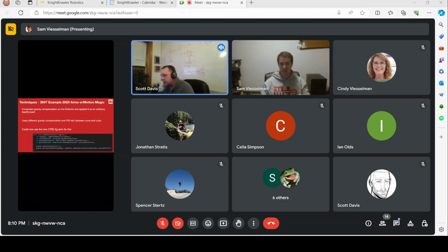Yeah, we are using a lookup table for all of our elevation. So we'll put the robot at 3 meters, shoot, find the angle that we want, and record that. Then we'll back it up a half a meter or a full meter and do it again. We figure out where we are based on the April tags, and I don't remember what our students have done there. I think that we did a really rough one, backing up every meter and recording the optimal values. But when they retuned it the second time, they may have done it with half meters or even less than that. So I'll check with them and see, but that's a good tip.